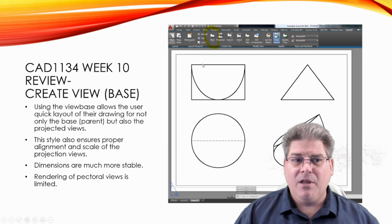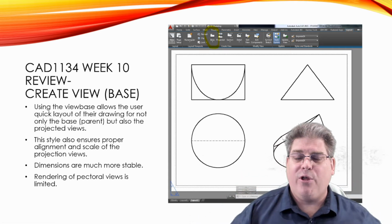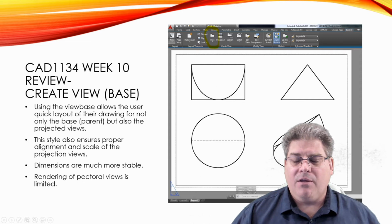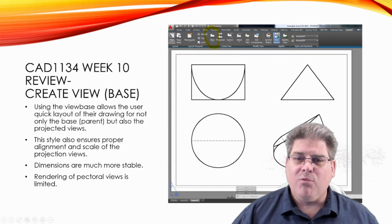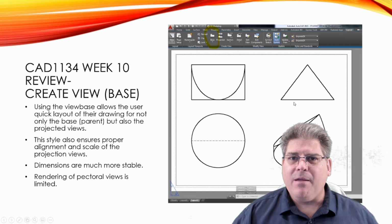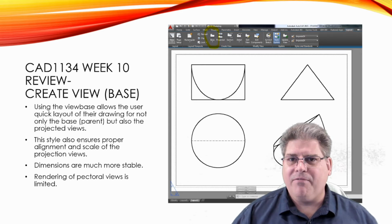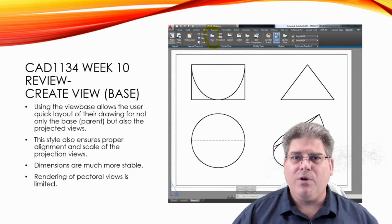In this case, the top ends up at the bottom, so we're taking that part and we're flipping it. So that's third angle projection. And we're able to lock the view so that we don't lose the association of our dimensions as well. However, if we try to use a rendered view on these, you'll find that it kind of is reminiscent of the 8-bit realm. So you end up with this kind of blocky resolution, and that's okay if it's good enough for you. If you want something better, then you can absolutely put in a viewport.